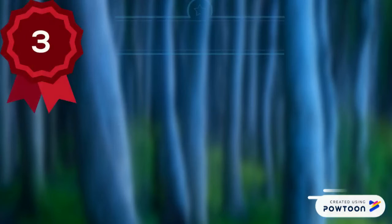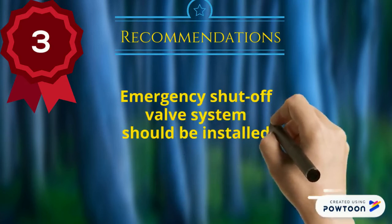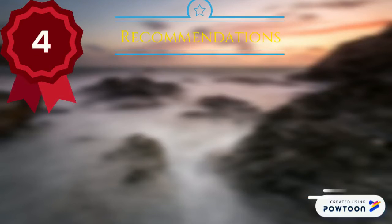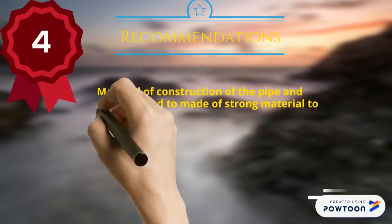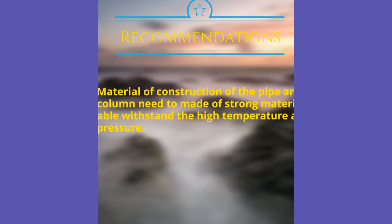Furthermore, the third recommendation is that an emergency shut-off valve system should be installed in the hydrolyzer. This is because sometimes there will be unusual situations. The fourth recommendation is that the pipe and the valve should be made of stronger material. This material construction should withstand the high temperature and the pressure of the fluid in the process.